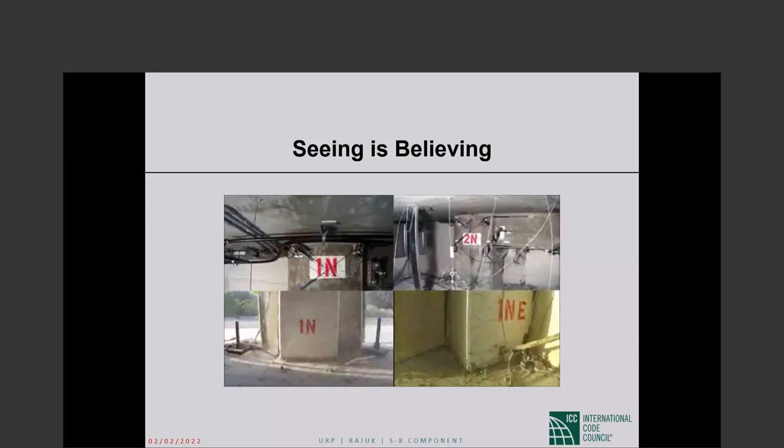What you apply, you design your structure for the specified dead loads, which include superimposed loads. You design your structure for reduced live loads. You design your structure for code prescribed earthquake forces. And this is where the load combinations come in.